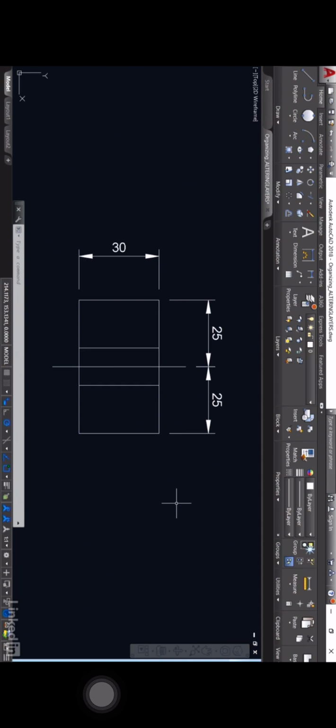Now, ideally, you want to change all of this so that the different layers have different line types, different colors, and so on. And they're all set by way of objects to the by layer setting. I'll come back to the by layer setting in a moment. Let's get everything on the right layers first. So if you go to the Home tab on the ribbon and look at your layer pull down here, you can see that we've got center lines, depth points, dims, hidden, and object. Now, all of those layers are available in this particular drawing. So what we need to do is put the objects onto those layers and alter the layers.